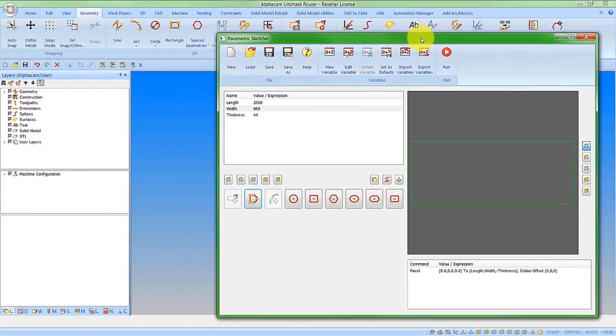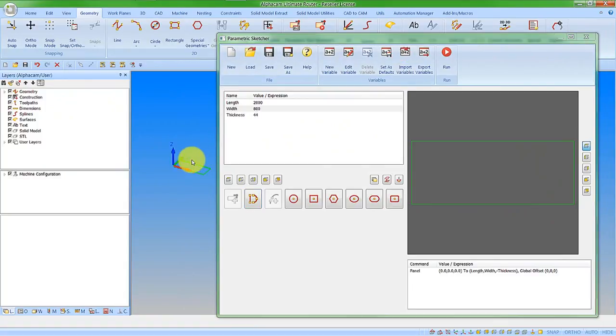Well, what I actually want to do is work with some machining styles, and in my machining styles they're attributed to user layers. So I actually want my features to be going on applicable user layers. So what I shall do here is want this panel edge to be on a user layer so I can machine around it. Well, we have the command here for setting an active user layer, but we need to specify these commands before we create the geometries.